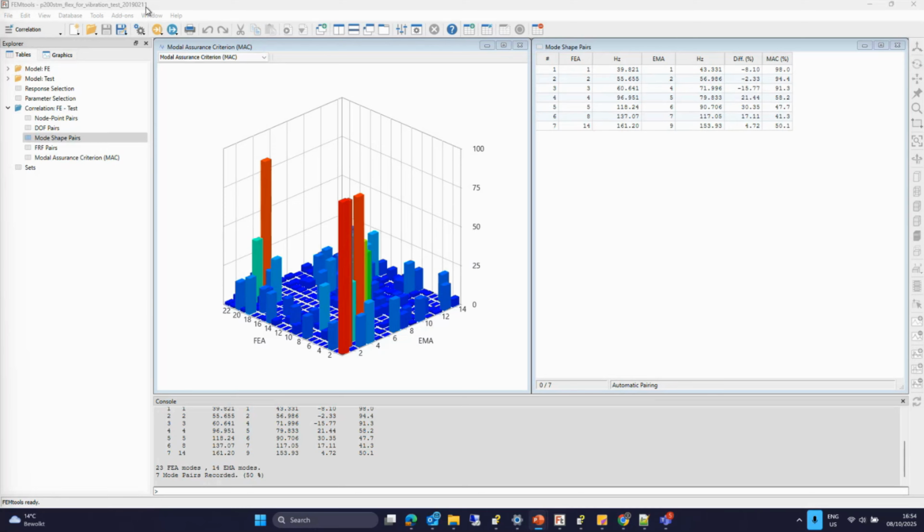if you don't use the param post -5, then you will instruct Nastran to produce them using alters. But by using that param post -5, it's fairly easy to get those files. And then we have a direct interface with those files to import them in FEMtools, so that modes and element matrices become directly accessible.